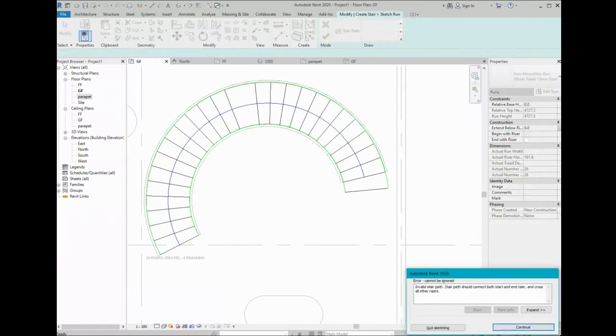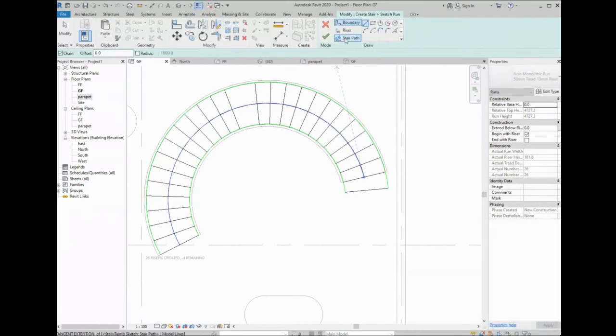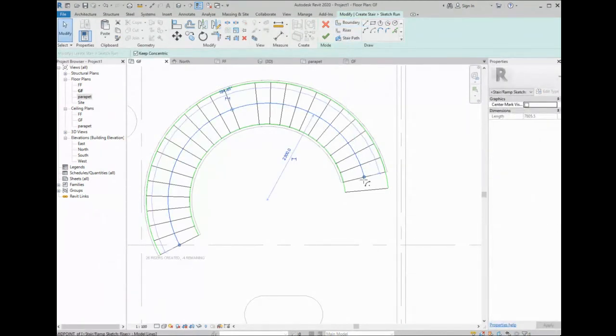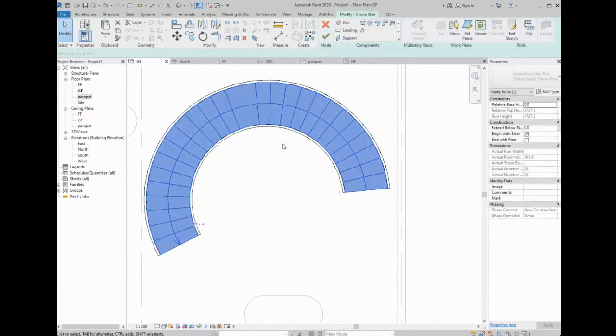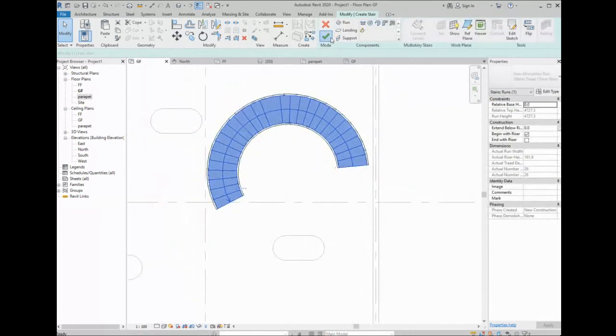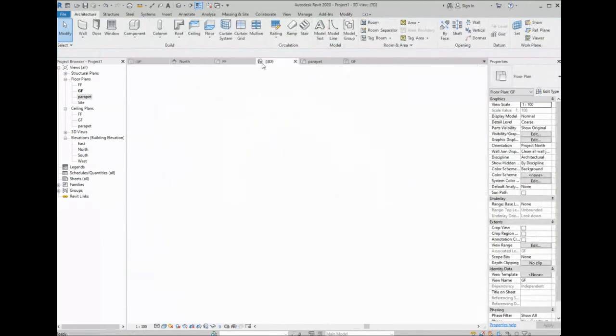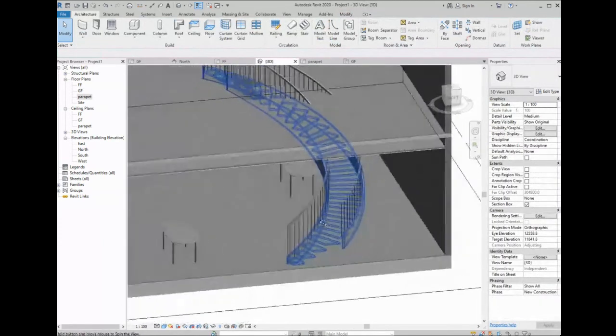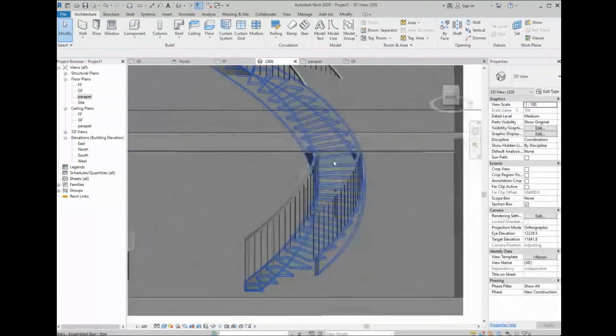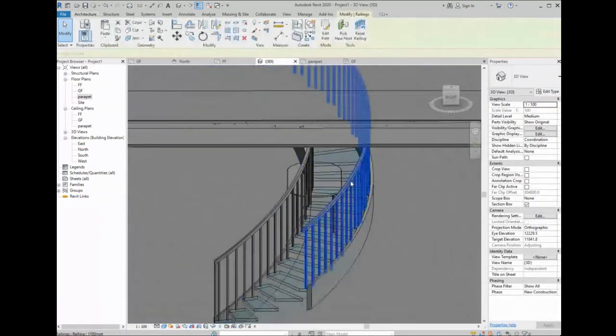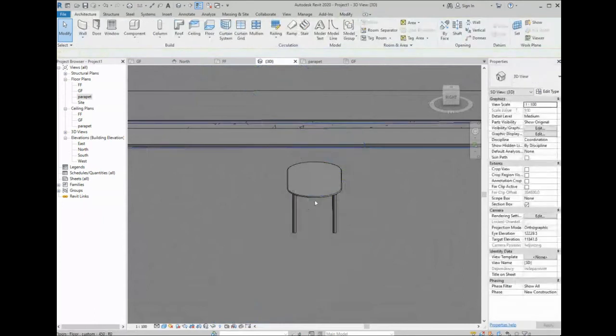But because, as I told you, this is okay. One more thing I forgot to change is the stair path. You can see that the stair path is until here, so I'll just increase it. Click on OK. Now it's done. Click on OK again. So now I have, for example, like a small landing here, and then I've increased the steps on this side. Okay, so you can see that this is now done. So this is if you want to edit.